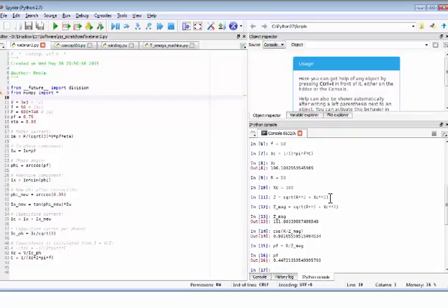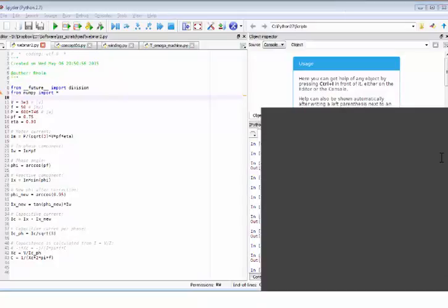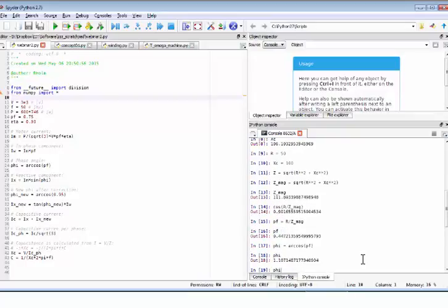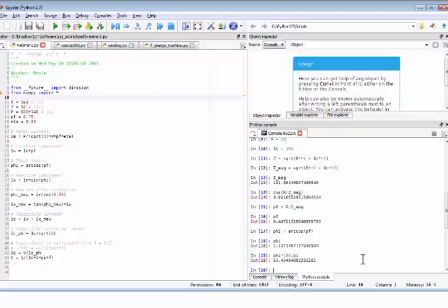But what we can do now is say, right, the power factor is equal to cos phi, so phi would be equal to the inverse or arc cos of this. So see if this works out. Phi would be that multiplied by 180 divided by pi to convert into degrees. Then you get 63.4 degrees, which is what we have also in the slide.